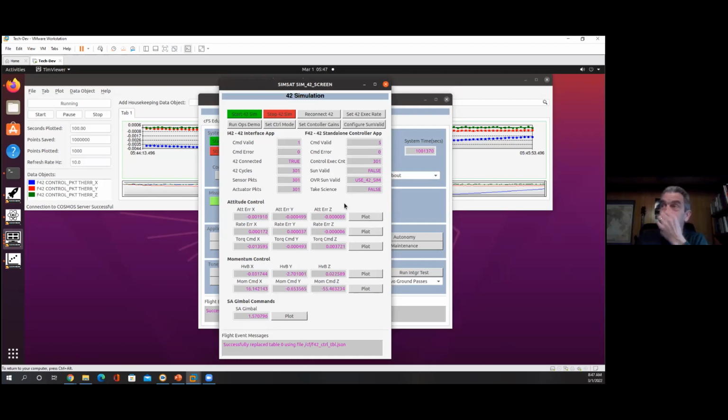And one CubeSat I'm helping right now, they just want it based on the latitude. And they want to just turn science on and off as they go over the poles. I see. There are a lot of operational things like that. Okay. And one of the other things that helps that I don't have shown here, we'll have a fault detection and correction running in the background. You want to keep checking that you're within the performance that you say you're going to be in, unless something's gone wrong.